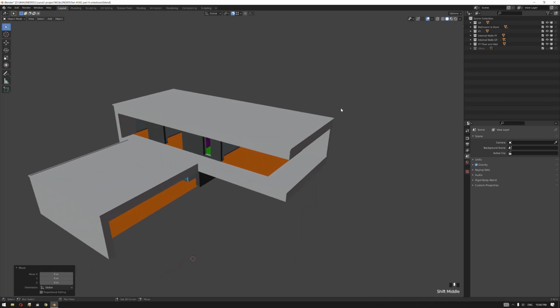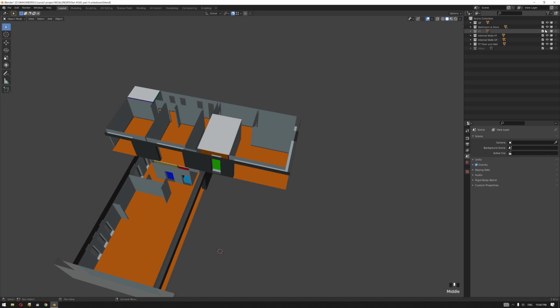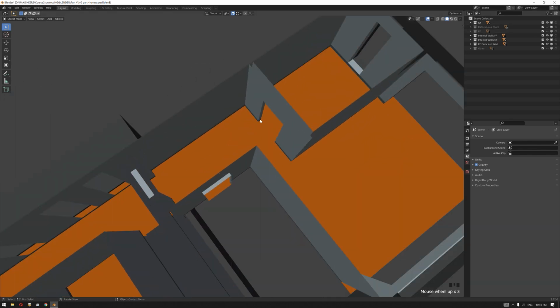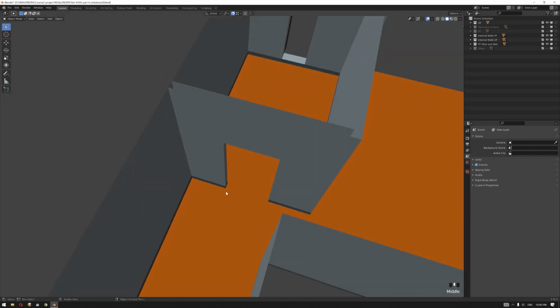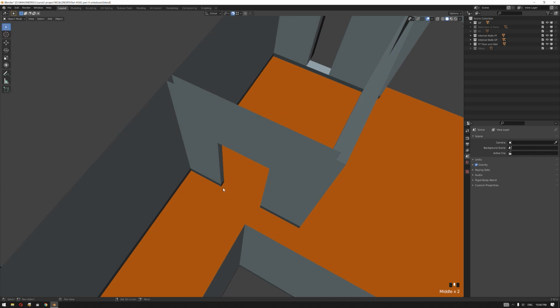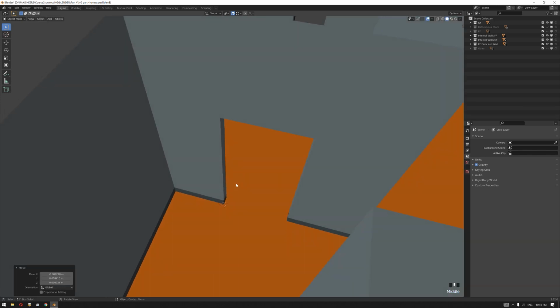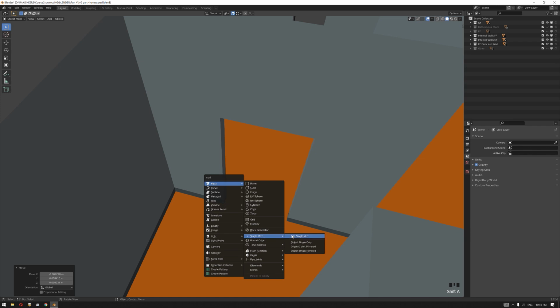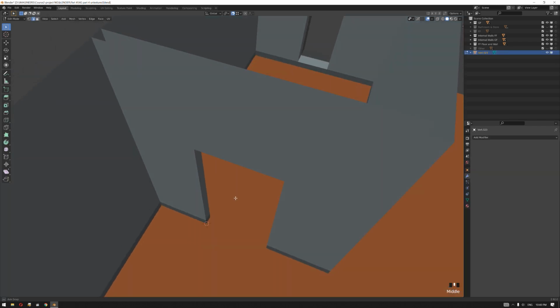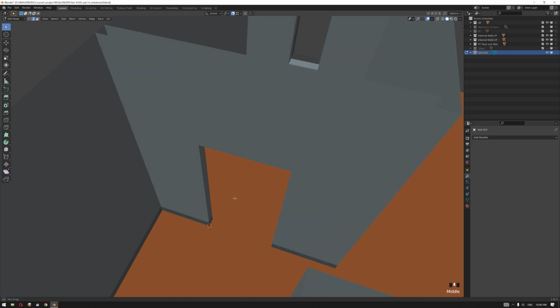So we'll start by modeling the door. We'll first hide the outdoor walls and also the bathroom. And let's pick this point and let's drag our 3D cursor here by pressing Shift and right click, and then let's add a single vertex to start our modeling of the door that is composed of three parts. That's the frame, the door itself, and the door handle.